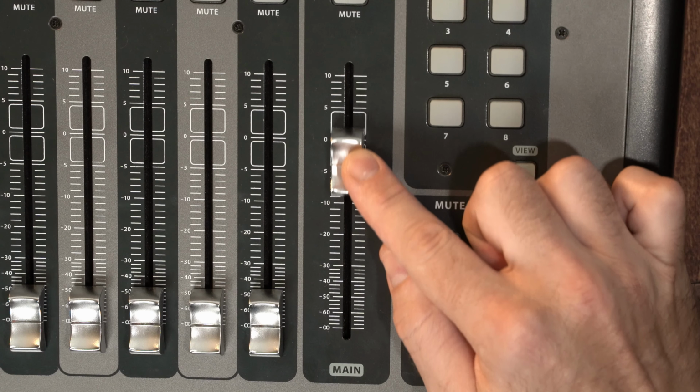And one of the reasons that this often results in this low input gain on the console is because if we do have our speakers turned on and all the way up or really high, and our faders are at 0, one way to limit the volume coming out of those speakers would be with a preamp, because the preamp would be the only other thing stopping our signal from our microphone getting out to the speaker, because we've left an open path from the microphone to that speaker.